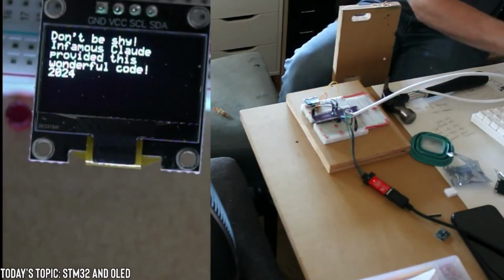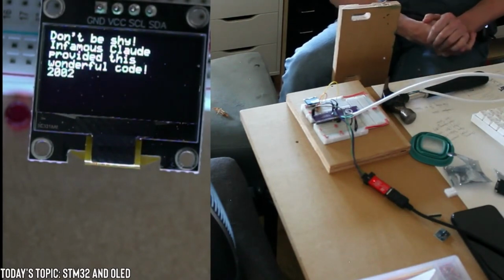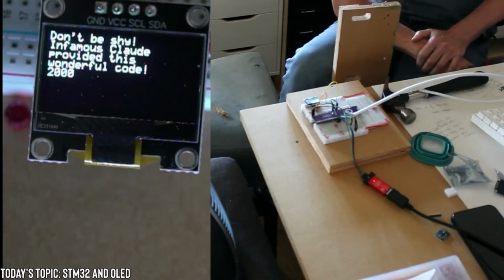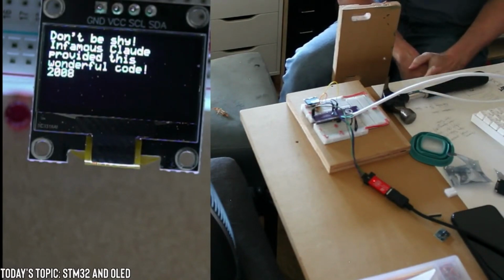I'm going to change this down to, oops, a smaller number here. Well, no, it doesn't matter. This is only when it changes. So if I bring this stuff back out, you'll see change. Well, we're trying to get the shock. I think a piece of rubber is going to dampen it where you won't see anything at all. So you can see it's hovering around 2000. That's the midpoint. That would be 0 Gs.